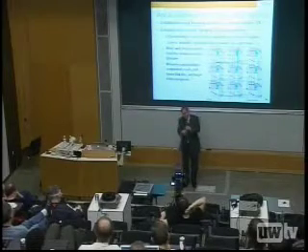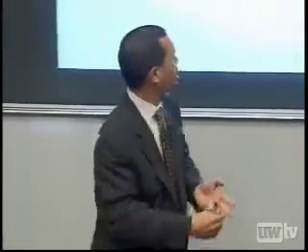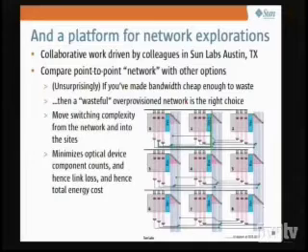It costs me 1/16 of a waveguide. It costs me one optical coupler, which is about 10 by 10 microns. They're very small. So what I've made inexpensive is bandwidth. And what is expensive are things like in-fabric routing, arbitration over many, many chips, sharing resources like that. So when you want to waste what's cheap and conserve what's expensive, that points you to making a network that is really a point-to-point, over-provisioned fixed network.